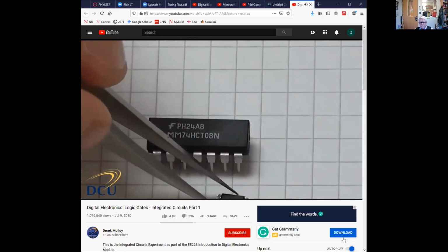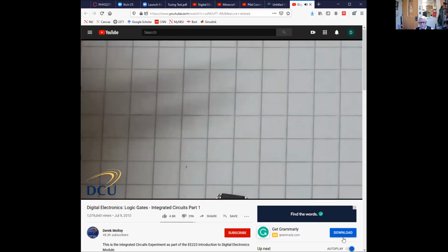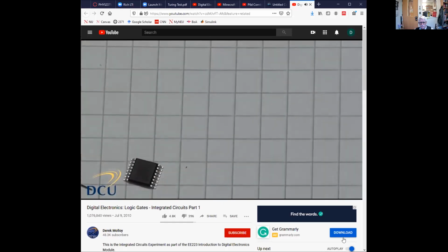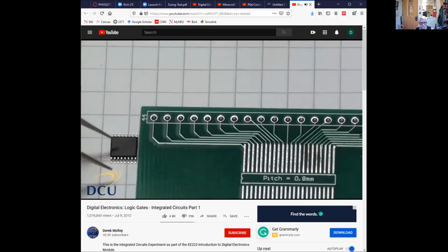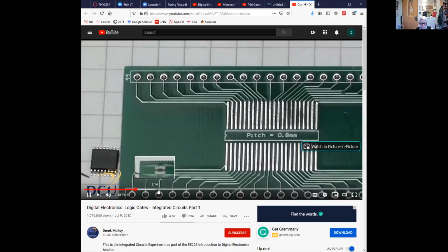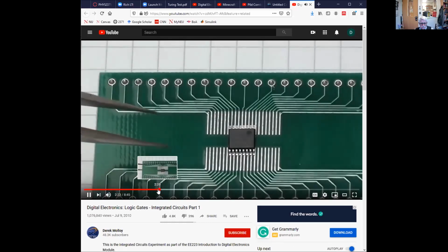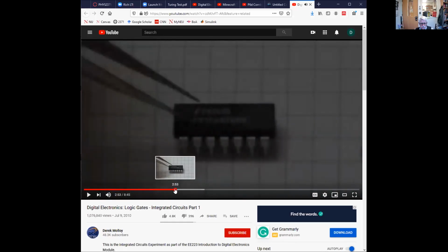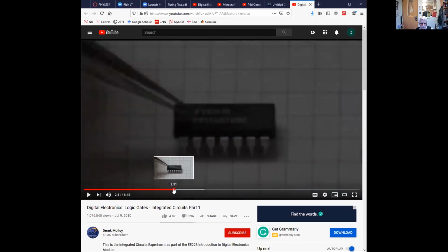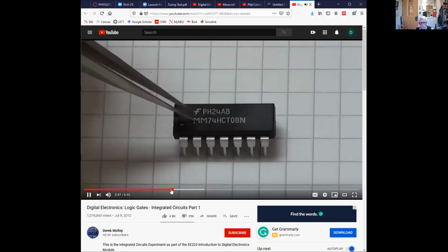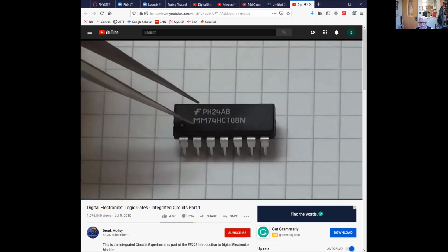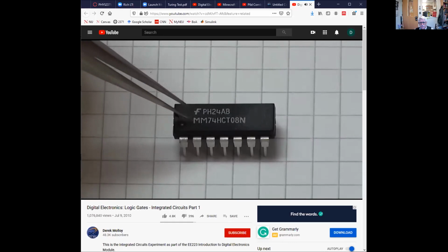It is possible that the chip that we want to use is only available in a DIP package, in which case we can use a board like this. It's a converter board. It allows us to change packaging format. The prefix could also be letters like S, which is the manufacturer Fairchild Semiconductor. It could also be letters like SN, which would refer to Texas Instruments, for example.